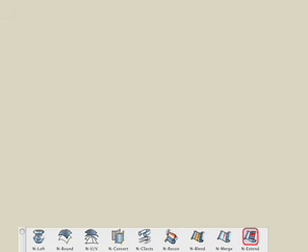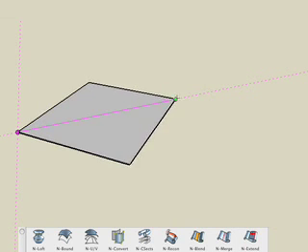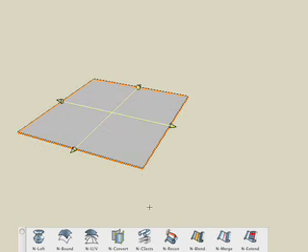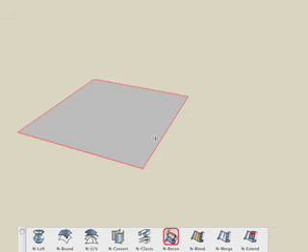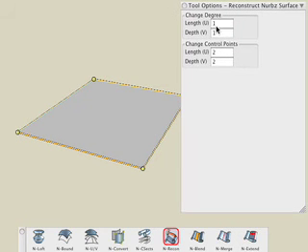Now let's examine the Nurbs Extend tool. We begin by creating a 2D rectangle, and we'll convert it into a Nurbs surface by using the Nurbs Convert tool and clicking on the 2D shape. Then we'll use the Nurbs Reconstruct tool to add more controls. In the Tool Options palette, we'll change the degree of smoothing to be length 3, and also the depth to 3 also.